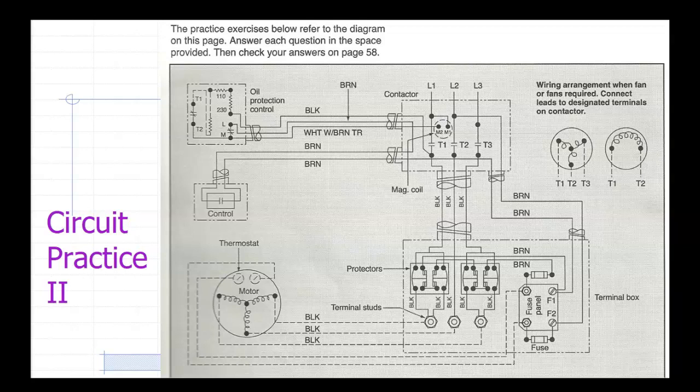Which incoming power lines provide power directly to the wires coming into the fuse panel in the terminal box? So we're looking at the fuses again. Got two wires. Follow them up. One goes to the control box, that's this one right here. The second one is coming up to what? You'll see? Directly to L2. It goes to L2. You'll see that?